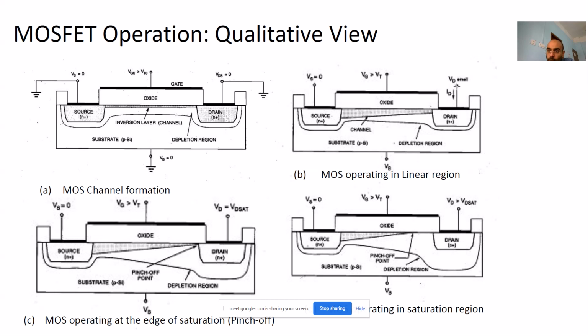Now we are just increasing the drain voltage, and that VD is, let's say, small. It's not a high value, we are keeping it small. So in that case, what will happen to the device? If you consider the difference, this is the second case, and in this case the MOSFET will work as a resistance. So the linear region operation, we'll consider this as the linear region.